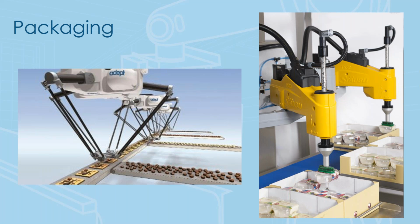So packaging application, or in this case, conveyor tracking. This is where you'd want to use a SCARA on the right, or a parallel Delta robot on the left. For conveyor tracking, we have a machine vision system mounted over a conveyor belt, and it's acquiring images of these parts as they go by. So we're getting position and orientation information for each part. And then after the camera has acquired the image, it sends that information to the robot, and the robot's tracking the movement of the conveyor and picking up these parts and then packaging them.